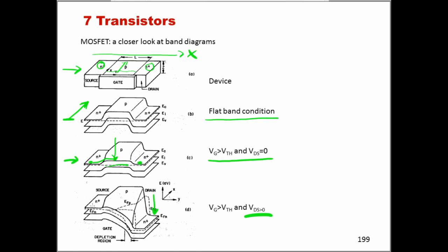So as we see now, an electron here can effectively and happily move into the drain side. But this would happen only very close to the interface with the oxide, as you can see, because an electron that is in the depth of the silicon substrate would not be able to do that, because it probably has to overcome a barrier that is too high.